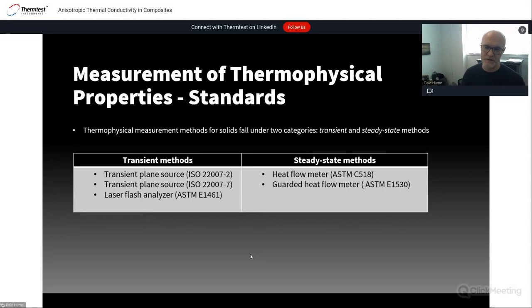And that lets us measure a much wider conductivity range with the steady state device. So that one is aimed at polymers up to metals, where the heat flow meter is aimed at mostly insulators. So both of those are really good for complex materials, heterogeneous materials, and or layers that are non-repeating in their thickness.